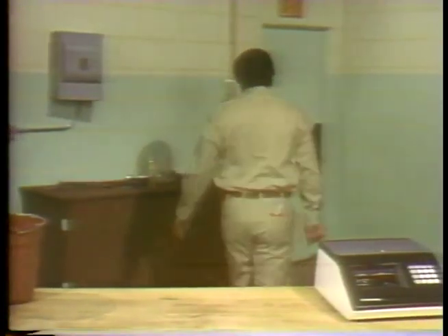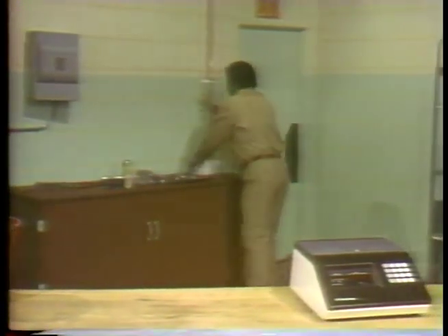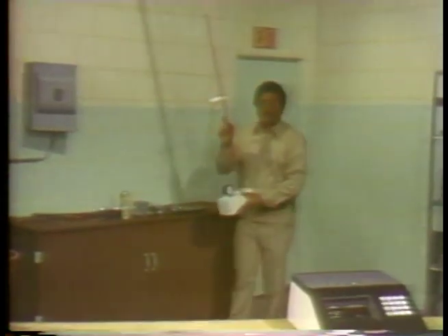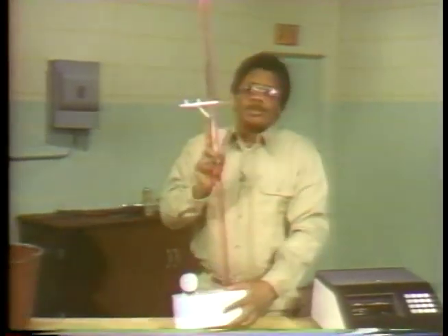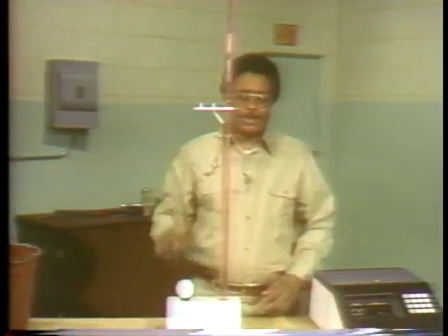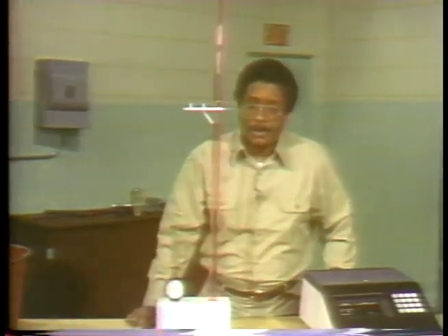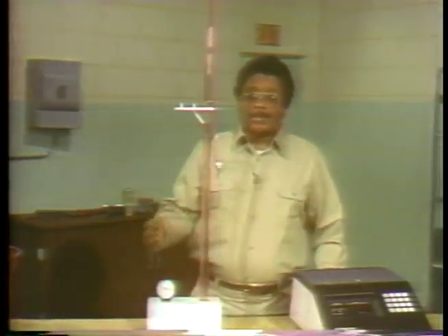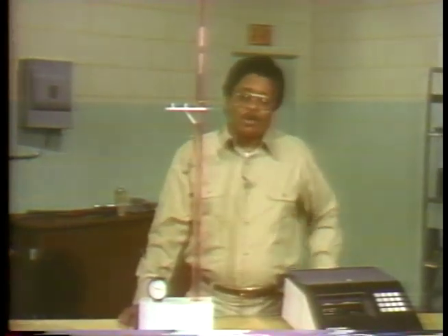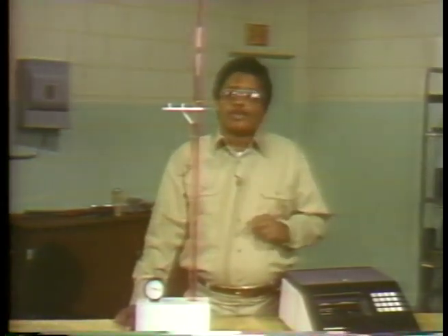Now, here's a column of water that's 5 feet in height. We know, from what we've done so far, that the pressure of a 1 foot column of water is 0.43 psi. So, a 5 foot column exerts 5 times that, or approximately 2.2 psi. The gauge connected to the bottom of this column shows this is true.